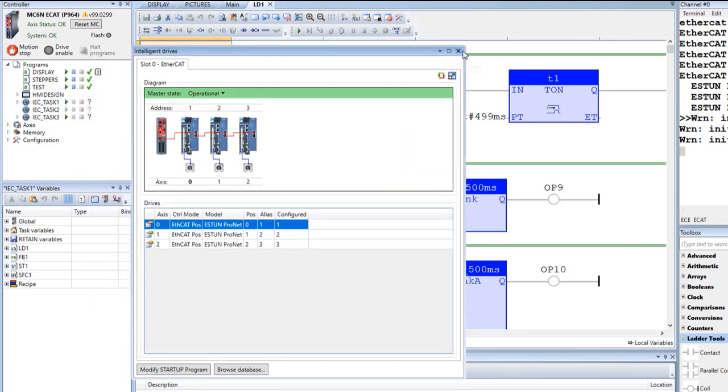That is for the EtherCAT part. If you have FlexSys devices control, this is not only for servo drives, you can extend it to any type of slave. You can have an encoder, you can have IO devices, whatever. It will just line up. Only the information that needs to be mapped to EtherCAT will be different. Here, obviously it's a servo drive, so you need position. For my IO devices, there is something else that you need to have.